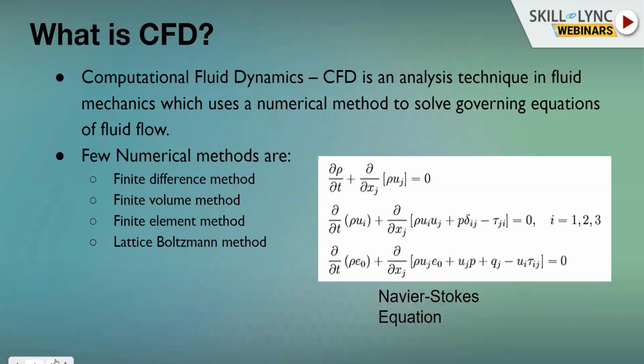And so what numerical methods are used? There are many methods available and being used earlier, and nowadays it is mostly the finite volume method. That's what is used in many commercial softwares, and it has become a kind of standard. The finite difference method is what you find in a lot of textbooks as well, and that is where it started. In the finite difference method, we solve the differential form of the Navier-Stokes equation.